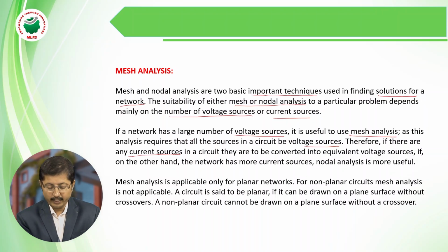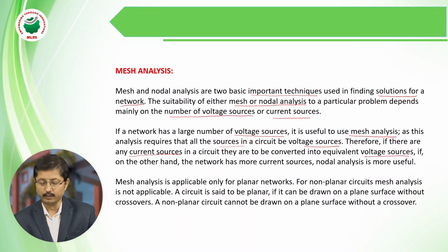So if there are any current sources in the circuit, they have to be converted into equivalent voltage sources. If, on the other hand, the network has more current sources, then nodal analysis is more useful. So this is the concept here.